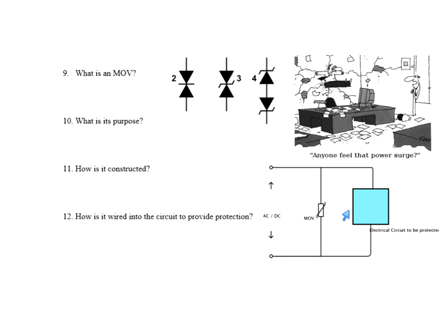So what is an MOV? It's a metal oxide varistor. It's built by putting two Zeners face to face, usually very high voltage Zeners, not low voltages like in a power supply. What is its purpose? It protects loads against high voltage spikes, or transients is the technical word, like lightning storms. That's a good thing that it protects against. So that's what they say here.